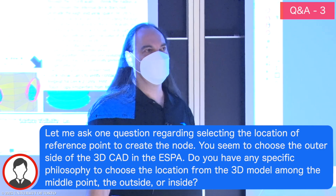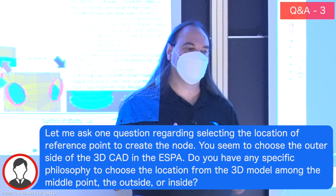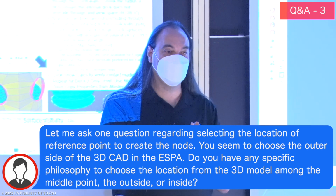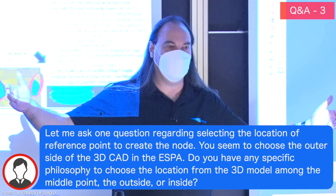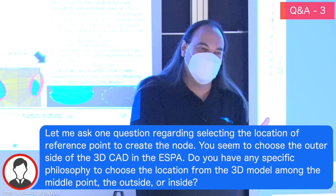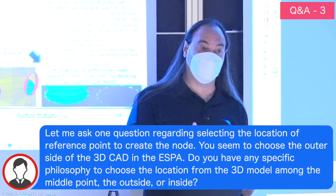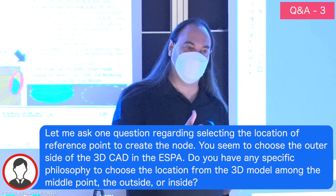So usually I choose the outside because that's the outer surface for radiation. Most of the things that we're doing are thin shells. So if it's a ½ an inch difference and it's 60 inches wide, that ½ an inch doesn't really make much of a difference. So if it's a thicker surface, it might not be reasonable to represent it with the 2D planar surface.